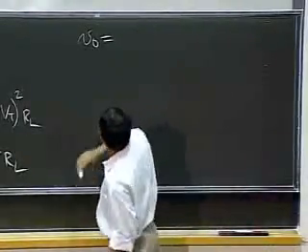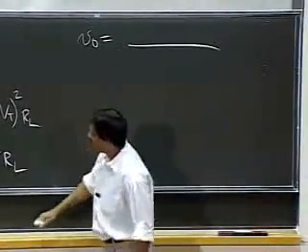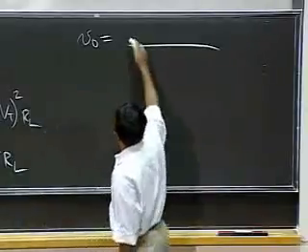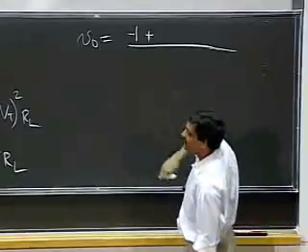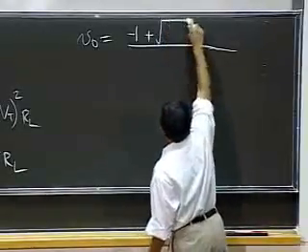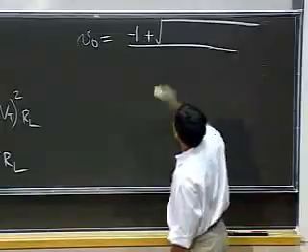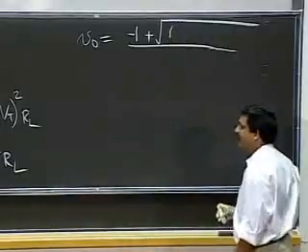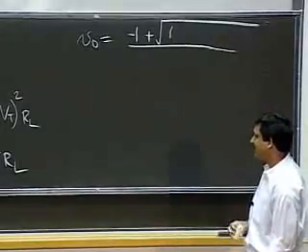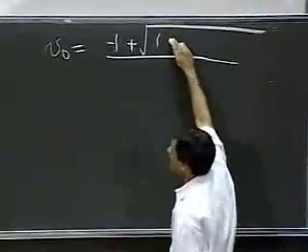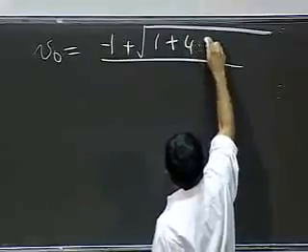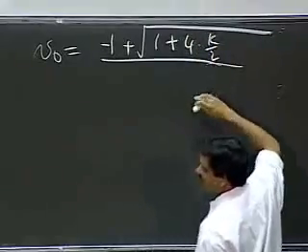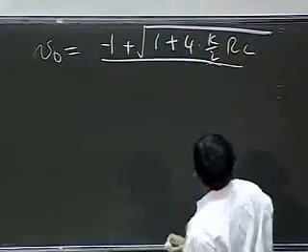And so I'm just going to get those numbers here. So the coefficient of V naught, that's b, is a minus 1. Take the positive root because we're up in the positive voltages here. And square root of b squared, that's 1. Minus 4ac, so I get a plus 4 times k divided by 2 RL.